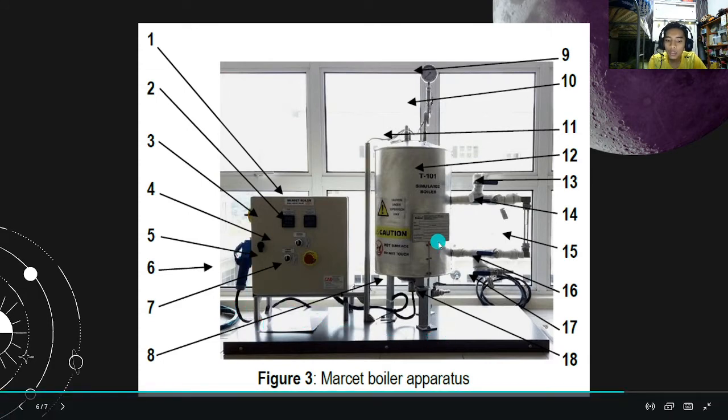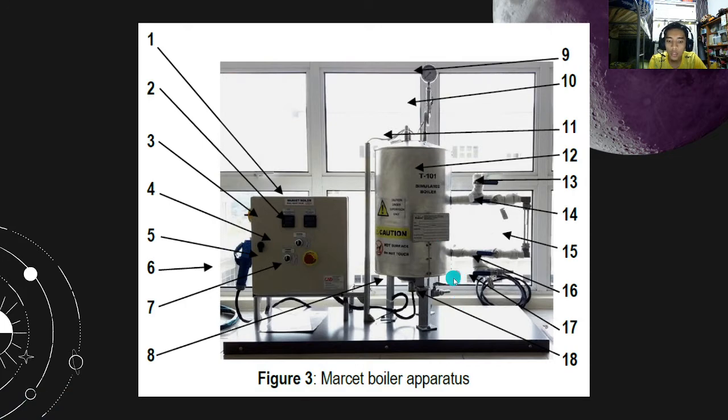And next we will open the valves labeled MVB 101, MVB 102, MVB 103, MVB 104 to the side glass, which is the MVB 101 is the 14, MVB 102 is the 13, MVB 103 is the 16, and the MVB 104 is the 17, the water supply valve. So next we will make sure the water level, this one, is half or more of the tank height,